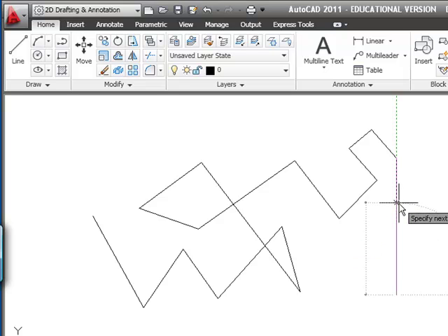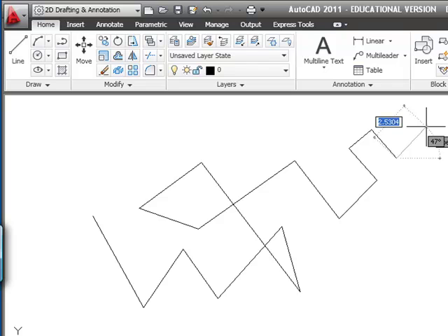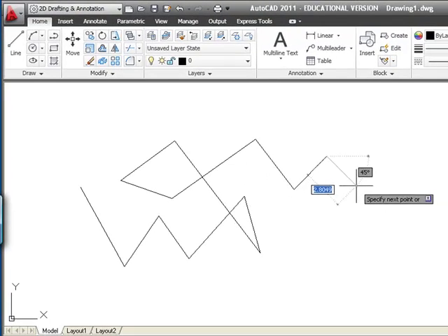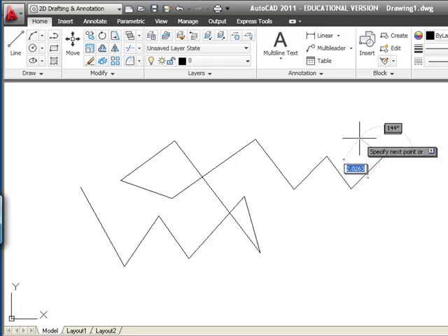If you strike the letter U on your keyboard and the Enter key, it will go back one selection point at a time, and it'll step backwards, and you can resume. Maybe you had an erroneous path going, and so you can go ahead and continue to select points.